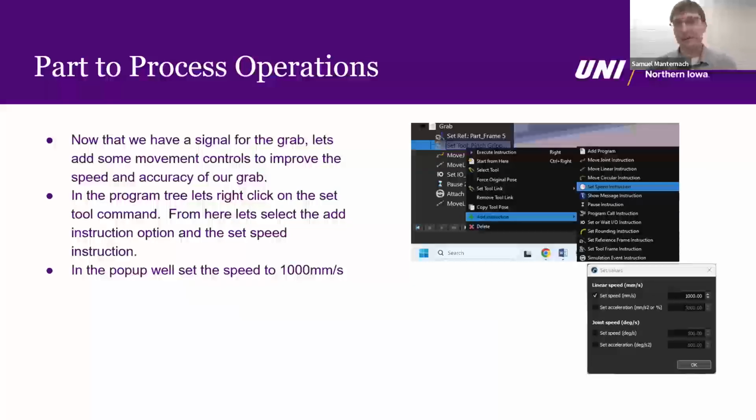All right. And then one final thing we're going to do in this robot program is set our control speeds so that we're able to do this operation quickly, but without a lot of danger for collision or damage. So in this case, we're going to be setting a very fast speed to be moving away from our plate, and then a much slower speed for the actual grab.